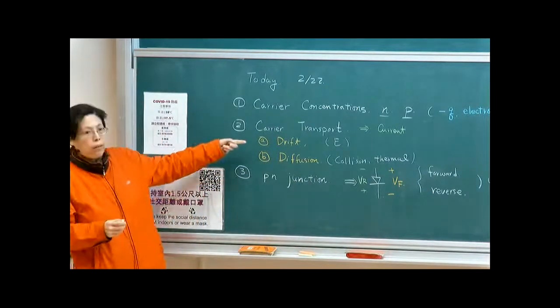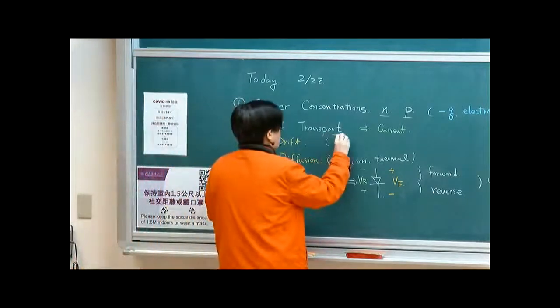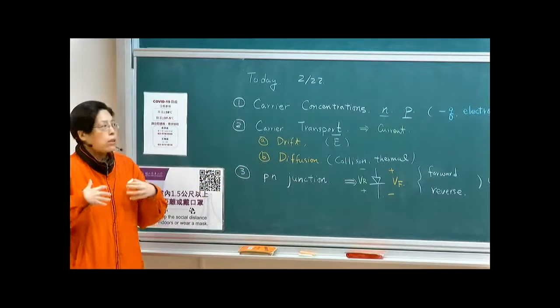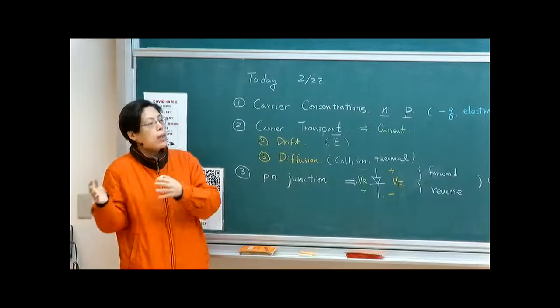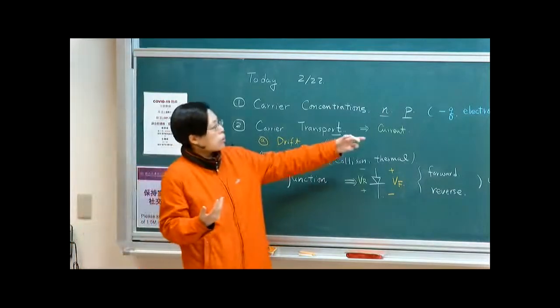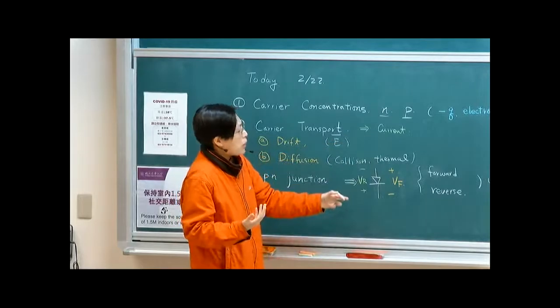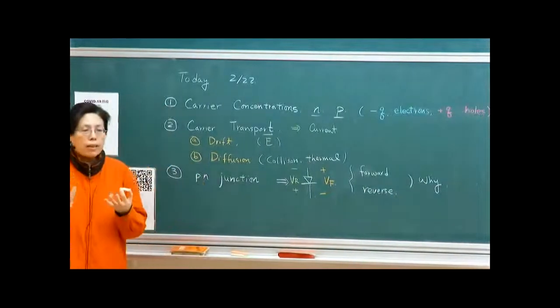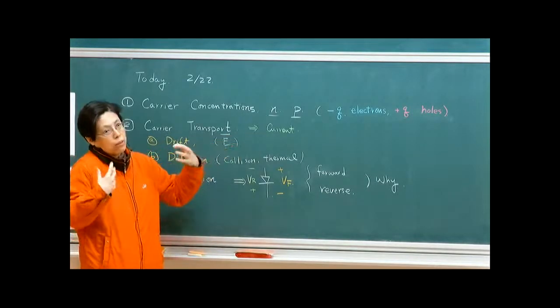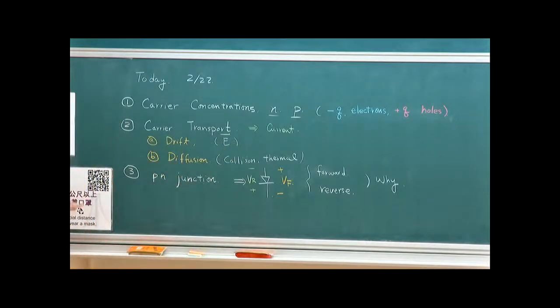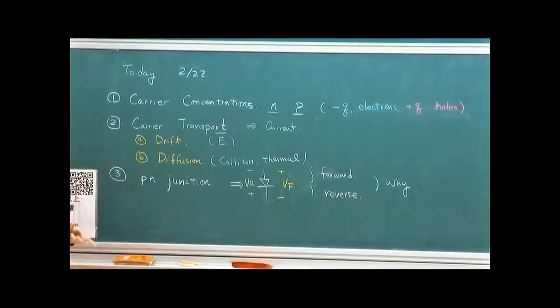Because these are charge carriers, if you apply an electric field, of course they will move. We call these the carrier transport mechanisms. And because these carriers are charged, when they move they create currents. So you then get current. That's the key thing we're going to link to devices, because as I said in the first class, we talk about elements. For each element, you want to know, when I apply a certain voltage, what is the corresponding current. That's the key in controlling electronic circuits. So we're going to talk about the forces that make these carriers move, drift and diffusion, and the balance between them.